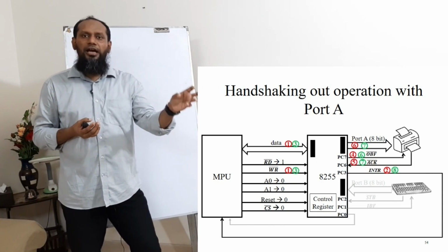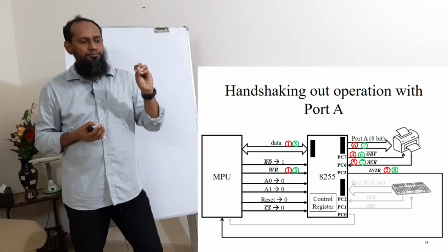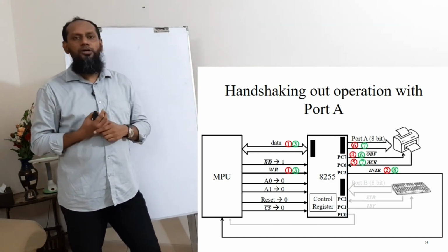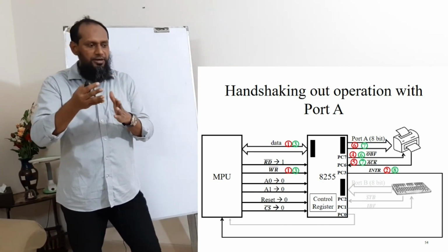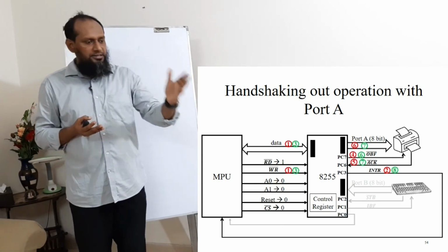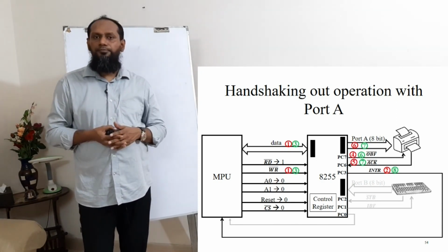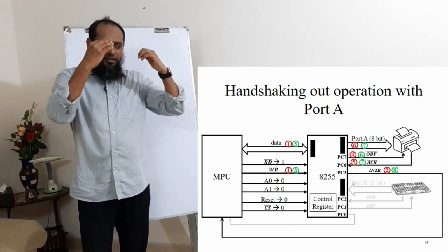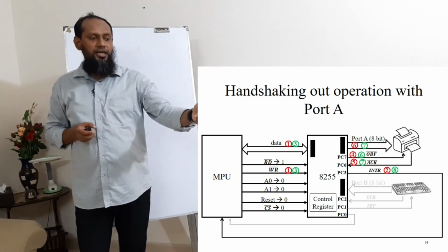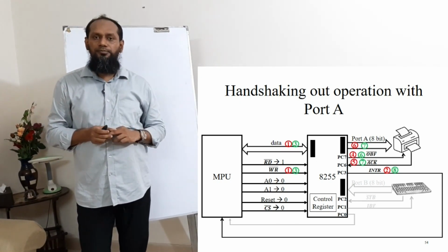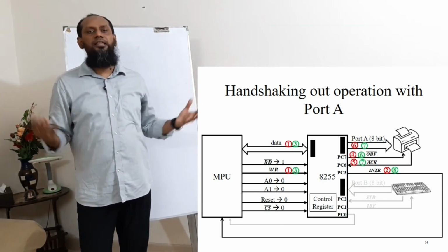So after receiving the whole data in the printer, the printer will generate an acknowledgement signal to 8255 or to PC6. So when it sends the acknowledgement, that means the data has arrived in the printer on timing 7. So after getting that confirmation, 8255 then deactivates the interrupt signal control connection. That means now I'm ready for another input, or now you can send me another data.